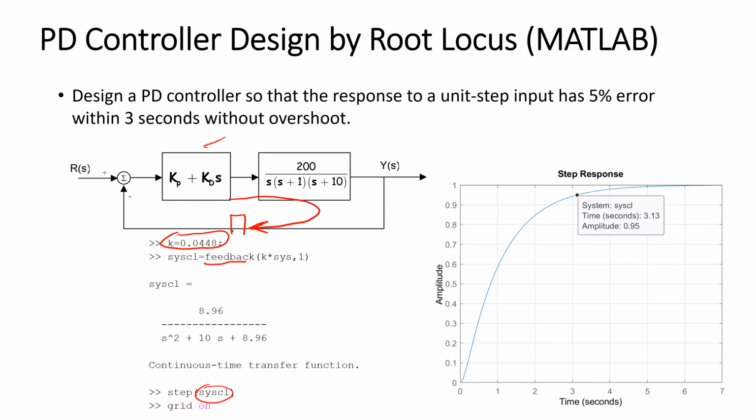And our sensor, the feedback is just only one. If the sensor has a transfer function, for example, if we have 10s plus 1 for the sensor, in the feedback you need to have 10s plus 1 to represent the sensor delay.